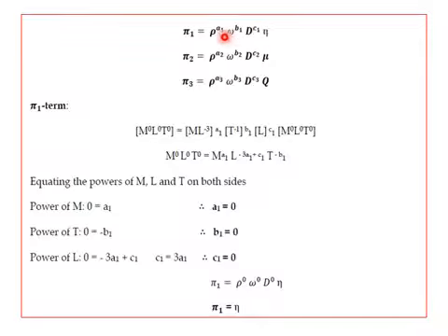Now writing here, rho, omega, d are the repeating variables which occur in all three pi terms, and they have to be raised to powers like a1, b1, c1, a2, b2, c2, a3, b3, c3. All the other remaining three become the non-repeating variables. For the first pi term you should always write the dependent variable. Since the efficiency was the dependent variable, we write it here. The other two terms remaining will be mu and q.